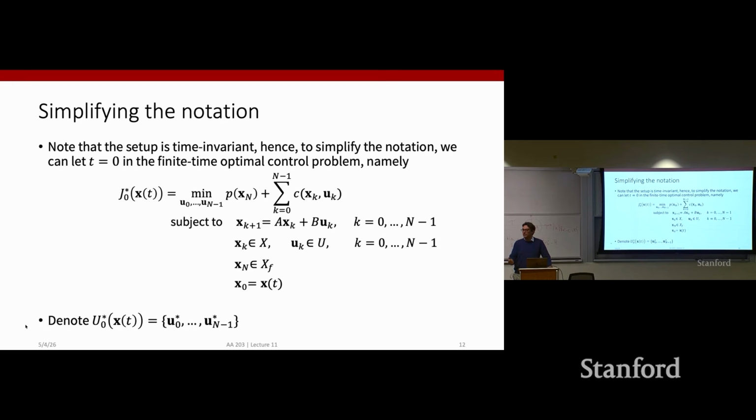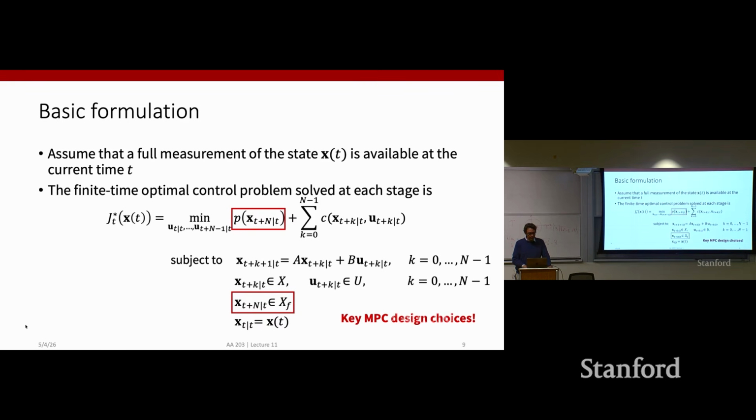That's why the time horizon, the terminal cost P, and the terminal constraint X f are crucial to tune, to make sure that you properly balance look ahead capability, so how long in the future you optimize over, which is in general, the longer the better. You make your decision more informed, but you pay more computation cost. And how short your horizon is, in which case you might be too greedy or even myopic, and you may not fulfill your task. So it's going to be a delicate balance between how much computation time you want to invest versus whether you can actually achieve your task.